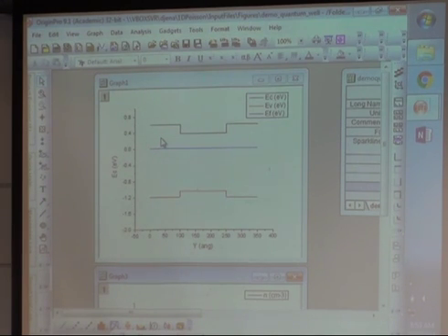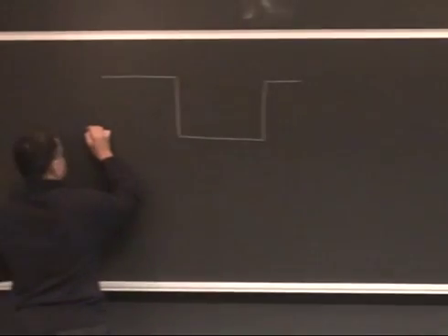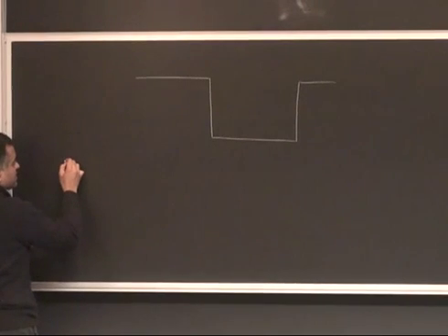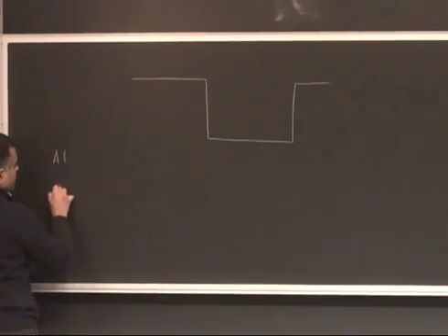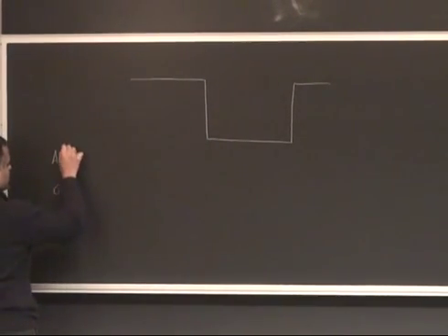And the whole reason it's called a HEMT, or a high electron mobility transistor, is because the dopants are put in the barrier, right? And what happens then is if I put dopants in a barrier, and here's a quantum well, and I put the dopant atoms, say this is aluminum gallium arsenide, I replace some of the aluminum and gallium atoms with silicon, right? So either this or that.